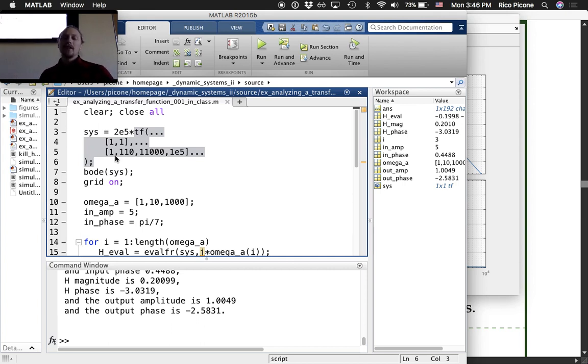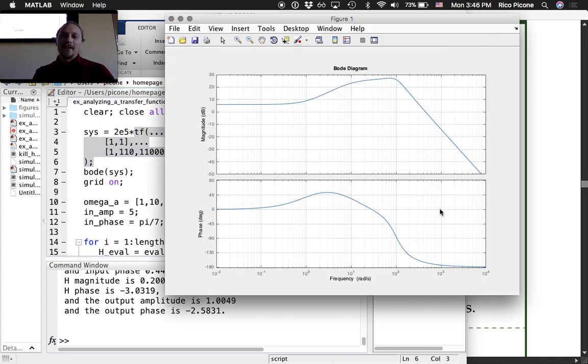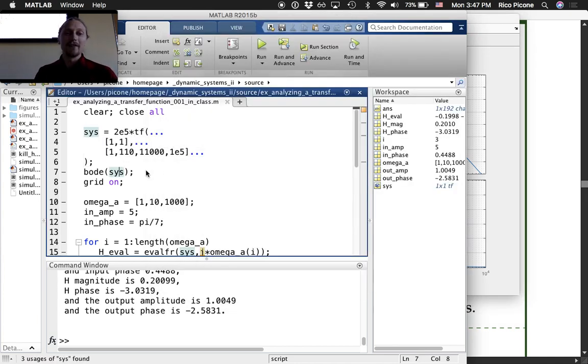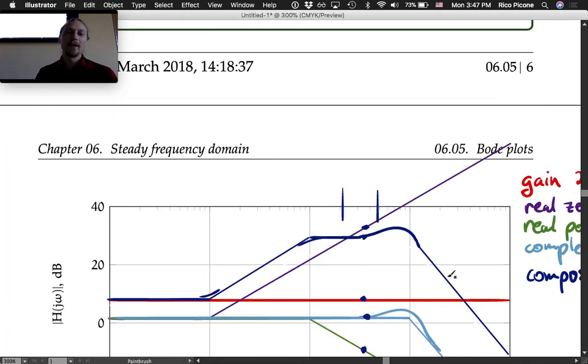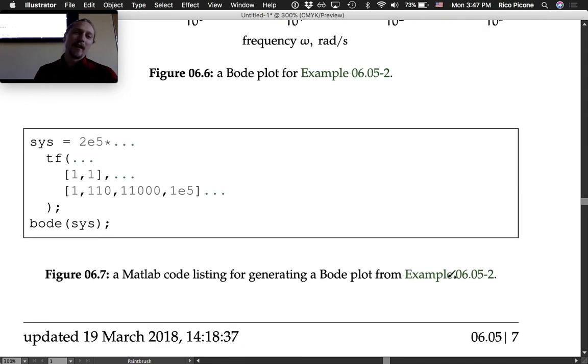So it's really useful, and if you just want a nice Bode plot, it's really easy to do. I encourage you when you're studying to know how to sketch them. You can arbitrarily make up a transfer function, try to sketch it, and check the right answer in MATLAB with 5 lines of code. I put the code in the notes. There's a line up here that was a hanging leftover that I didn't use, so you can cross that out.